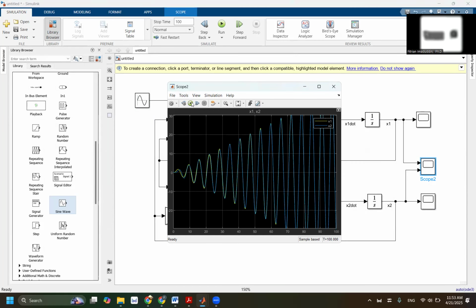Still have the resonance, because these two frequencies are the frequencies of omega n. So in single degree of freedom, you have one trap only. The trap is only at omega n, because you have only one omega n. But in two degrees of freedom, you have two omega n, so omega n in the first mode and omega n in the second. So this is what happened.